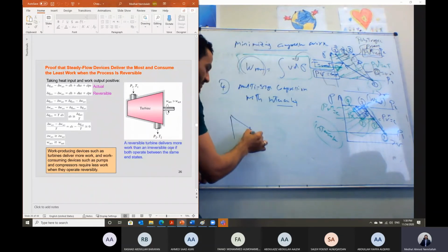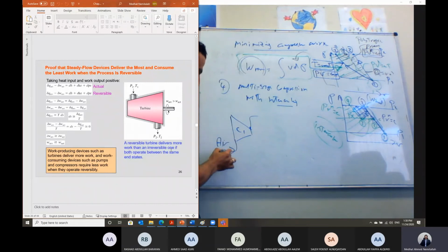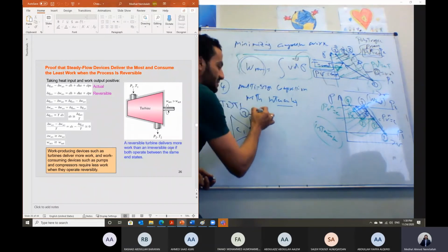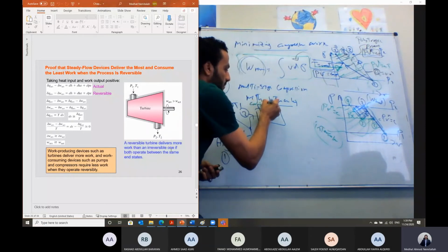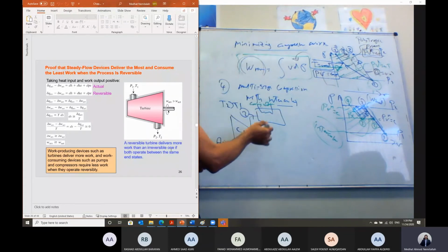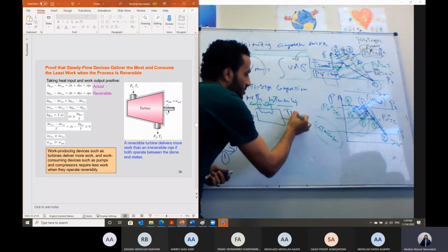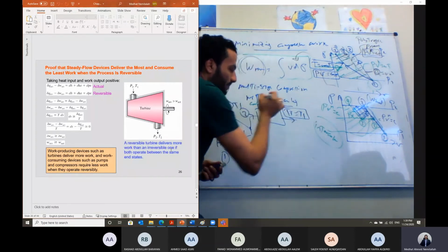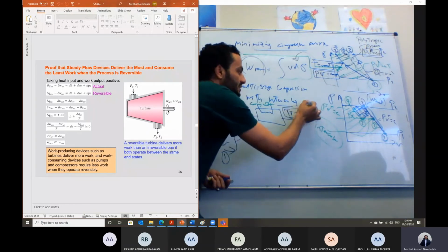So in this case, this is compressor 1. Let's say air is coming here at state number 1, and it is leaving at state number 2. T2 is greater than T1. I will just pass this air inside an intercooler. We have here cooling water passed to reduce the temperature. So the air will be leaving here at temperature T3. We call it complete intercooling, that means T3 is the same as T1.